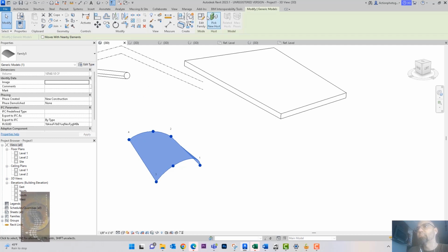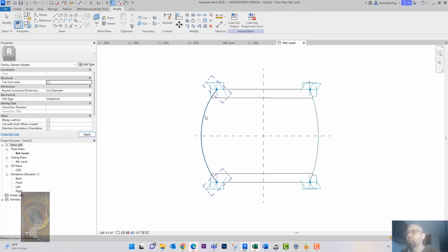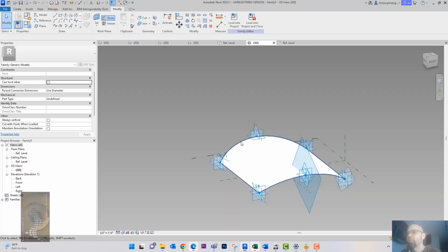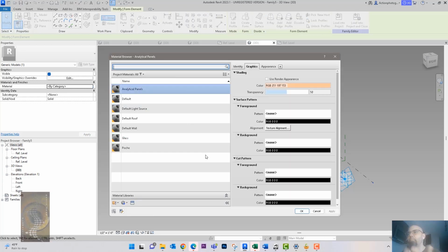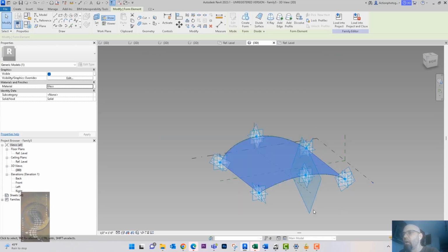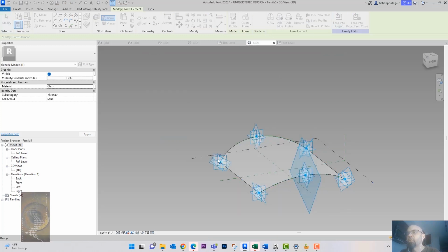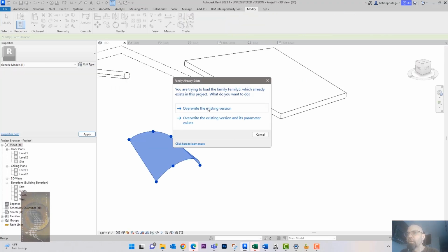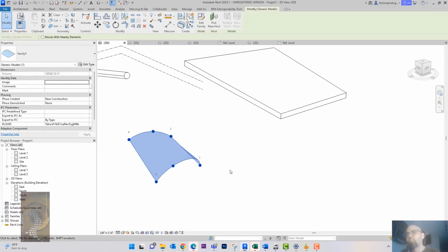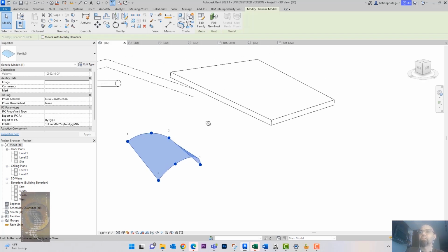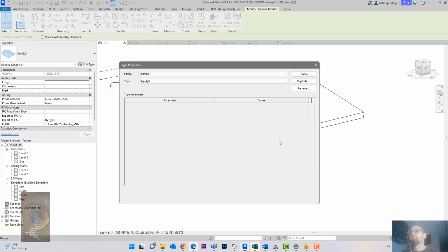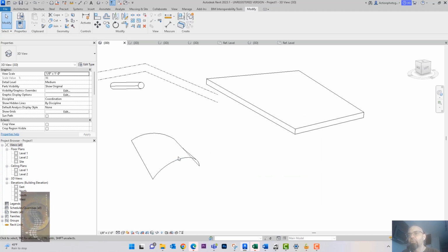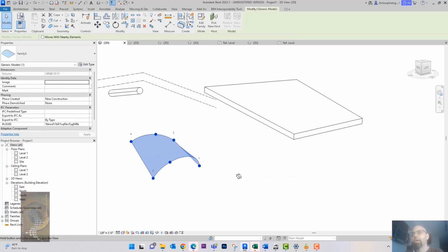And also I can grab this thing here. You can also put material on these as well. So if I come in here and grab the actual surface, you'll see that I can put a material on them. So I can create a parameter and assign a material to them. And just like all families, it didn't really place a material, it just put the default glass generic on there. But you can create your normal material parameter and add a material as well.